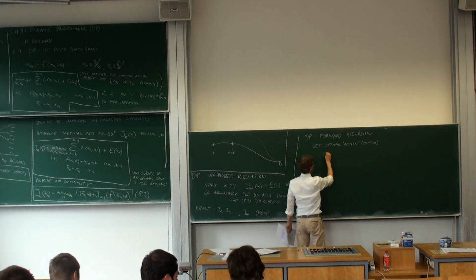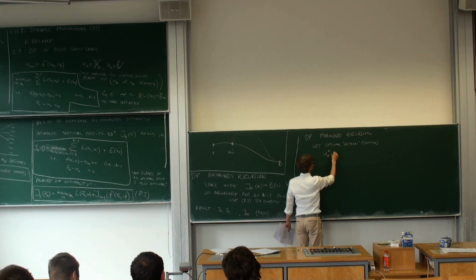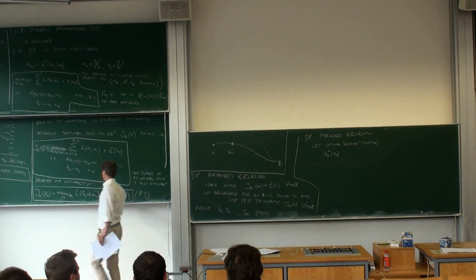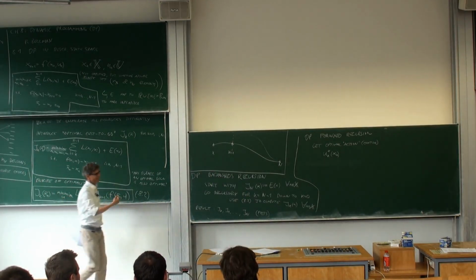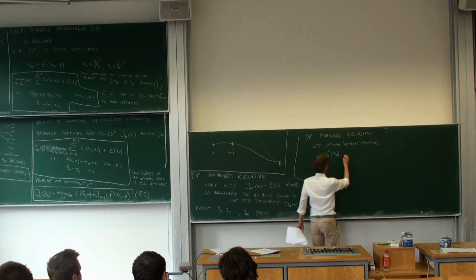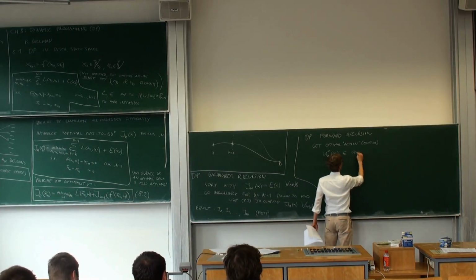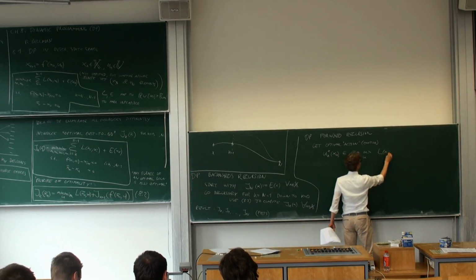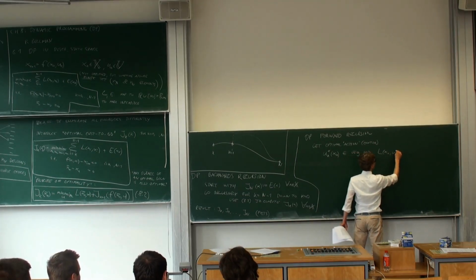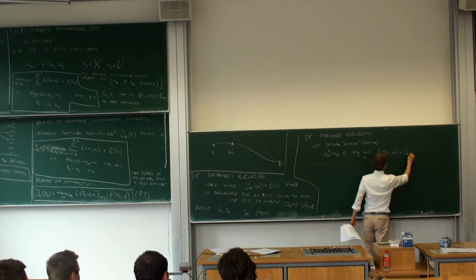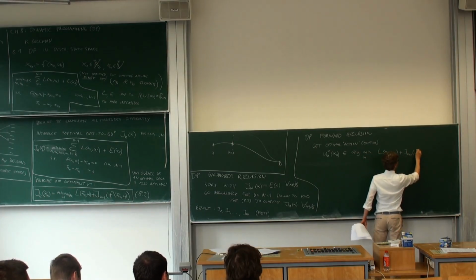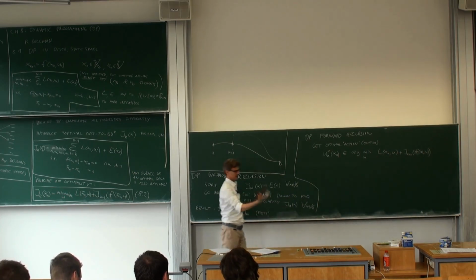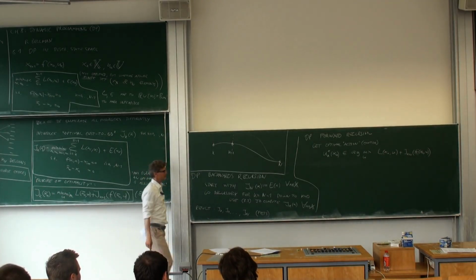From this, you just say the optimal control at a stage k, we know it. It will be one of the minimizers of this function. So it's actually possibly not unique. So I better write something like element of the argument that minimizes, over all u, this cost function that we had, L_k(x_k, u) plus J_{k+1}(f(x_k, u)). So that's the same expression, just that now we are interested in the value that minimizes it.